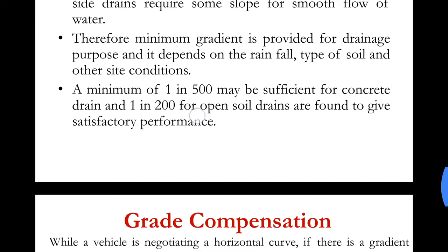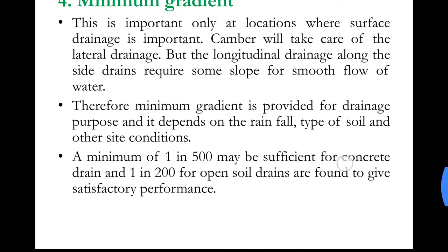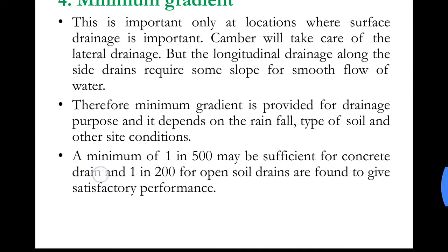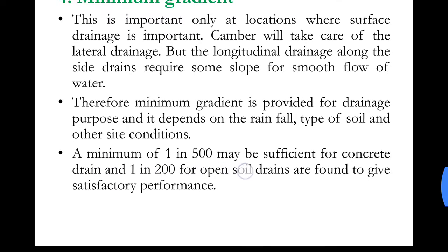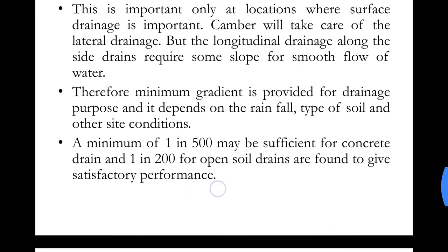A minimum of 1 in 500 may be sufficient for concrete drain, and 1 in 200 for open soil drains are found to give satisfactory performance.